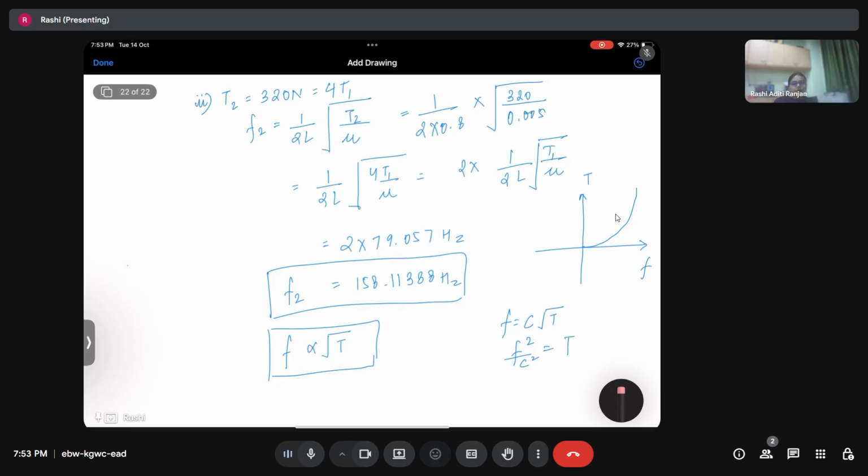Now, these are the fundamental frequencies, right? So how do we even want to control the fundamental frequencies? So the thing is that if let us say that I want to oscillate it at lower frequencies, and I want the second or third fundamental frequency to be less than 100 hertz, then what will I do? I will try to give a tension such that my first three frequencies come under 100 hertz. But now I want a case where I want all my frequencies to lie above 200 hertz.